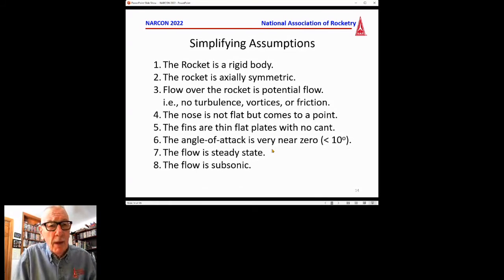The simplifying assumptions, there's a couple of them that are crucial to model rocketry, but most of them are the same assumptions I would make in deriving the equations for sounding rockets or full-size rockets, and actually could be used for regular launch vehicles too, except that launch vehicles have a very specific capability, and that is their thrust vector control and stability control that allows them to control their stability without fins, and therefore be less responsive to wind and aerodynamic aspects.